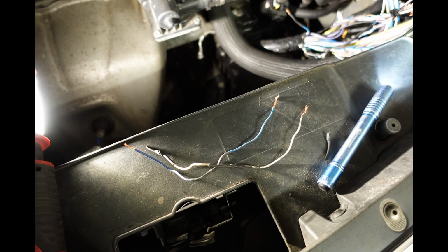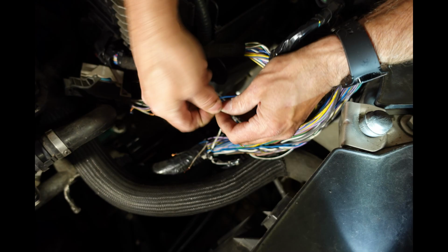So, you know, I can see it on a scope. I have communication back to the fuel pump control module. Is it the right communication? I think somebody broke a bunch of splices in the harness and actually put them back together the wrong way. So this will be an interesting one. I got some snapshots of that. I'll go ahead and throw them up here if I can.